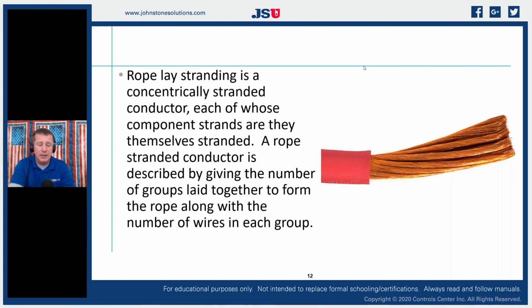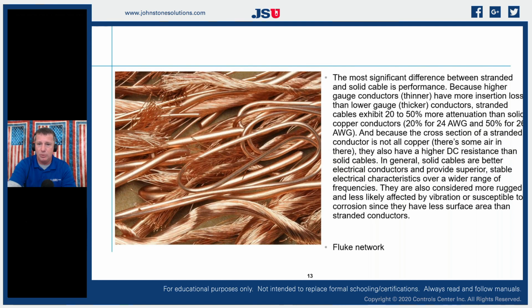You see this a lot in cord style, like SO style or in SJ cords, that they'll have the multi-strand like that. And a lot of automotive wiring, if any of you ever wire up any kind of high current wires for automobiles, especially automotive amplifiers, a lot of those use that braided or rope style, so that it has multiple layers of braiding to it. It's pretty strong wire, but very flexible.